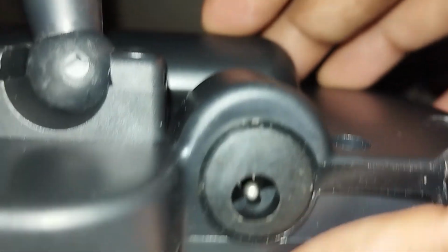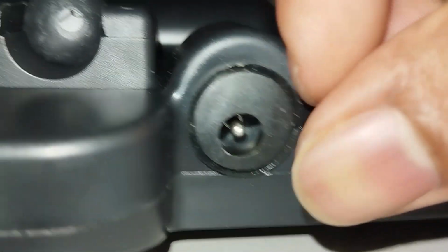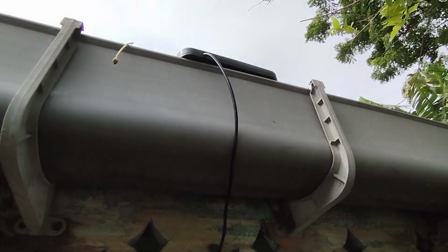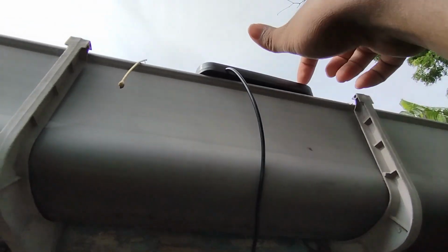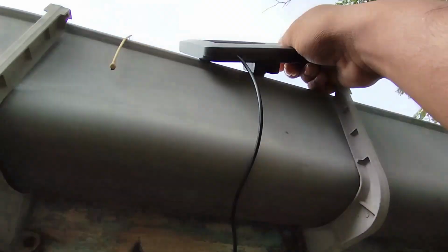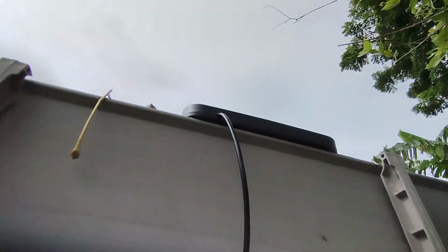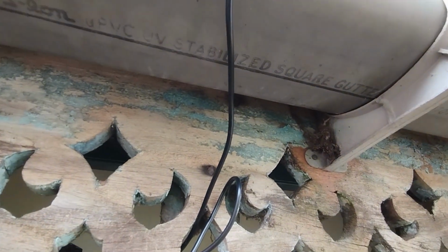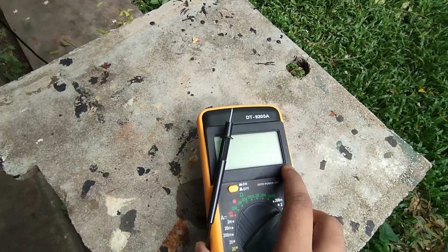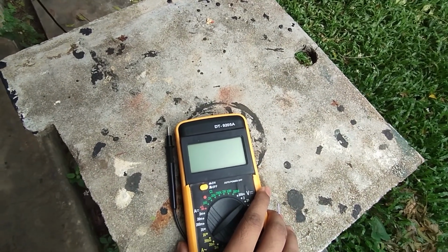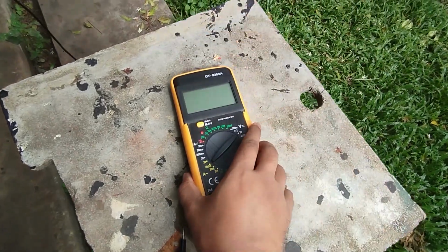There is also a socket part on the lights, because that is the power receiving socket. Then I have the testing part, where I placed it under very low sunlight, delivering 6 volts at open circuit voltage, because today we have very low sunlight without any color grading. Even in that sunlight it delivers 6 volts, but after plugging in you can get different results, because that is no longer open circuit voltage; it is under load, because the battery is getting charged.